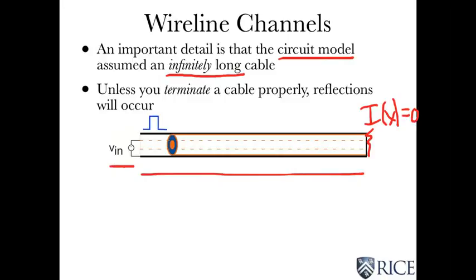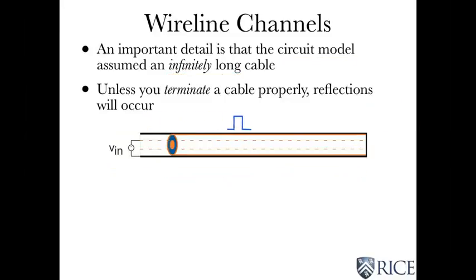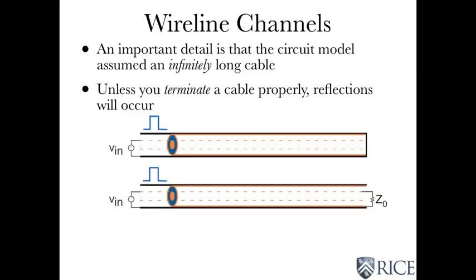What happens now, suppose the voltage source from the transmitter sends this little blue pulse. We know it's going to propagate, but look what happens because of the improper termination: you just cut it, so it bounces back. And it bounces back theoretically with no attenuation. This greatly affects the transmission properties of the coax. You get the same thing back again, and guess what? If the impedance looking back that way is not right, it's going to bounce again and again and again. It's going to go on forever.